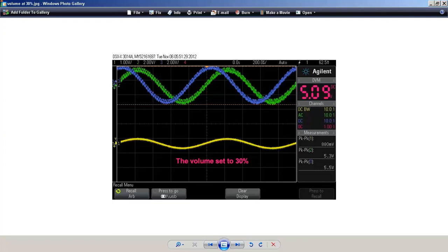The output is now just beginning to show a little bit more distortion. This is, again, the switching frequency of that 300 kilohertz or 305 kilohertz, well beyond the audio range. So this has no effect on the audio. The audio is just as clear and as clean as you could expect. You don't hear any distortion. This is all out of the audio range, so you don't hear that.